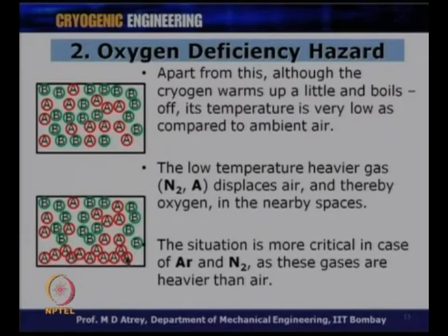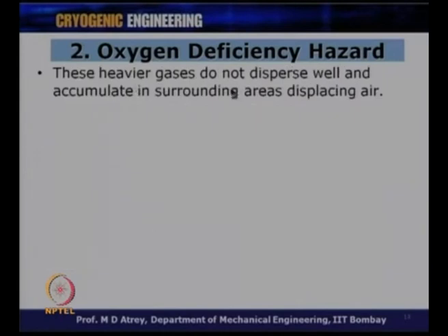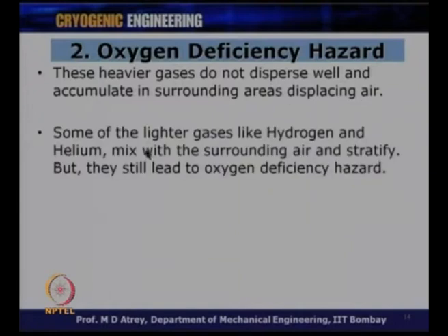So, you can get subjected to a nitrogen enriched atmosphere around you, or an oxygen deficient atmosphere around you, which can lead to asphyxiation. So, one should see to it that such gases are not around you, or they will not replace or displace air around you. These heavier gases do not disperse well and accumulate in the surrounding area, displacing air. Some of the lighter gases like hydrogen and helium mix with surrounding air and stratify.